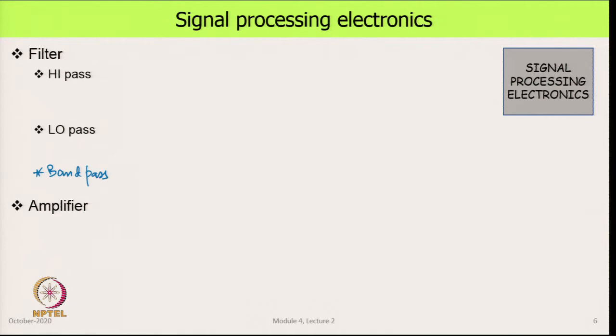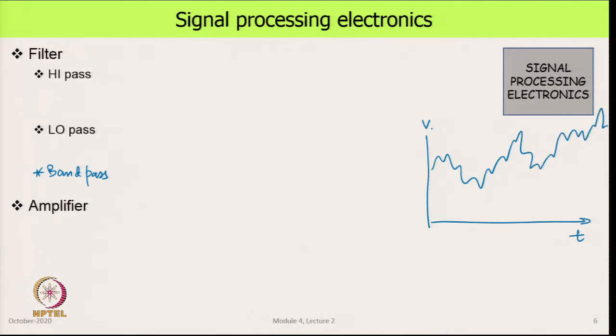So, what we are saying is that we take the signal, which is time versus its voltage or the magnitude of the signal, and typically a sensor will produce something that goes like this. If it is changing with time, it will show a trend. If it is steady, it may just show something like this, and this is all completely random. So, this sort of signal, each one of these wiggly things, can be broken up using a Fourier transform,